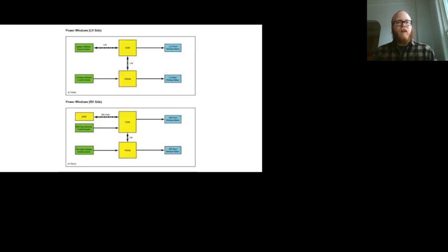And then a very, very quick look at LIN networks. LIN networks are newer. Well, they're also older, but they're coming back onto the scene, so let's just call them newer. So these are one-wire networks that work between two modules. There's like a master module and then a receiver module.